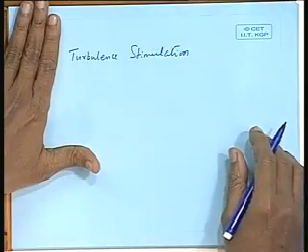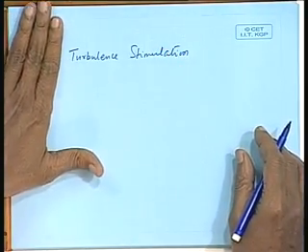We have to stimulate turbulence in the fore part of the ship. And how do you do it? We will have to introduce artificial roughness at the front end of the ship, so that the flow becomes turbulent because of existence of rough surface. As if we are introducing forcible turbulence on the ship forebody.